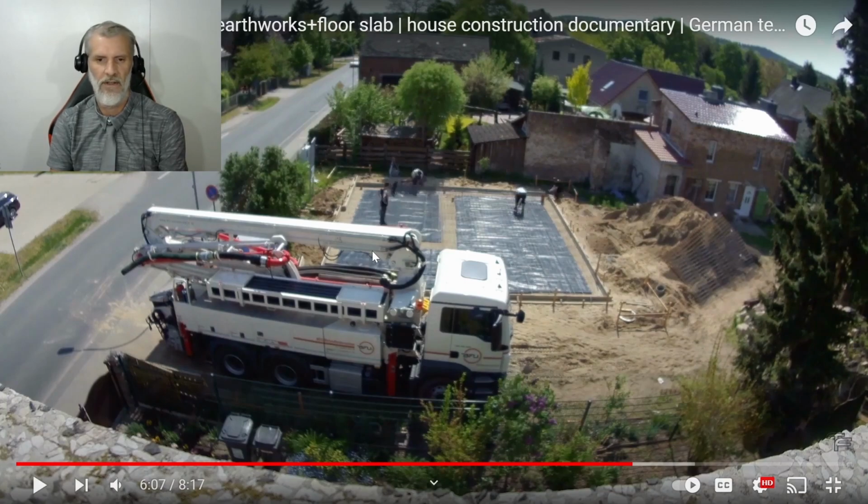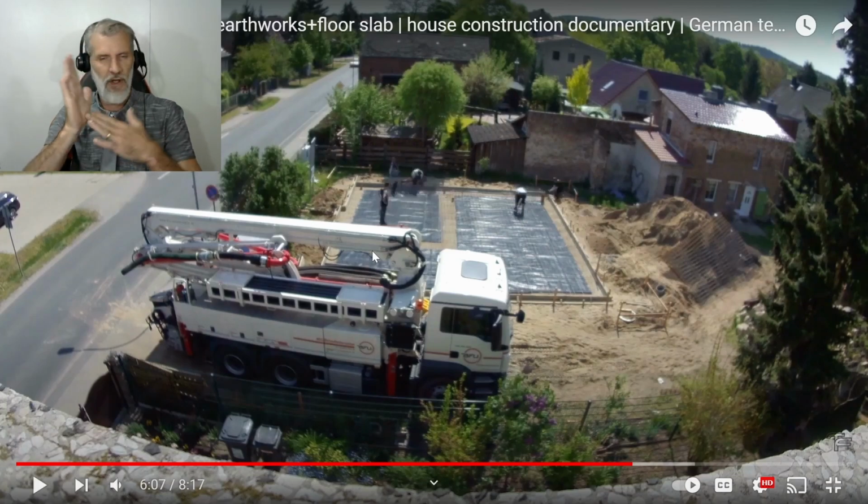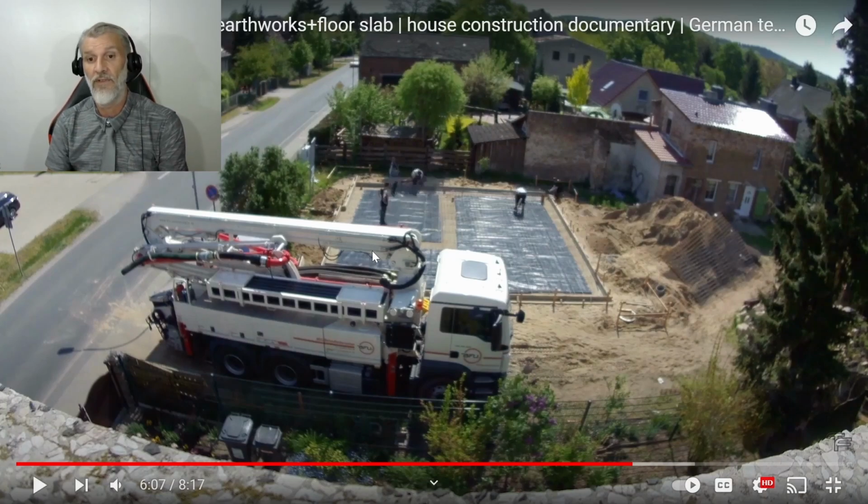The slab dimension is the basis of the building, and if you have a problem with your slab, everything else is out. Anytime a tradesman makes a mistake, that reverberates all the way through. It affects the bricklayers, the carpenters, whether your walls are square, and the installation of kitchens, doors, the whole lot. So the slab is the most important part, because that gets everything square straight away. And if this is square, everything else is easy.